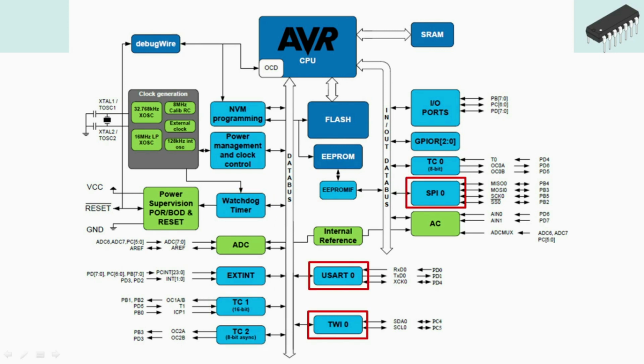The microcontroller supports 3 serial communication protocols, mainly SPI, TWI, and USART. The Serial Peripheral Interface, SPI, allows high-speed synchronous data transfer between the device and peripheral units or between several AVR devices. The in-circuit programming used to flash the bootloader and application uses the SPI protocol.